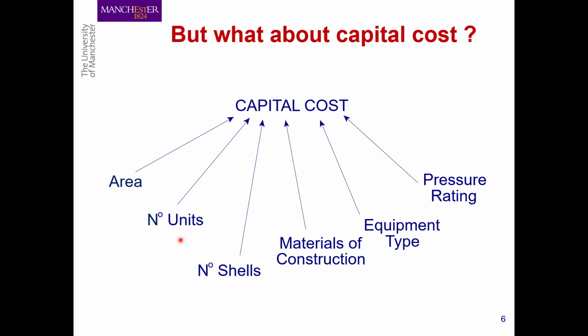However, exchangers employed in industry may be 1-2 heat exchangers. It means that it has one shell and two tube passes, or 1-4 heat exchangers, one shell and four tube passes, or even 2-4. It means that it might have two shells and four tube passes. And these designs can involve cross flow, countercurrent flow, or partially mixed flow.